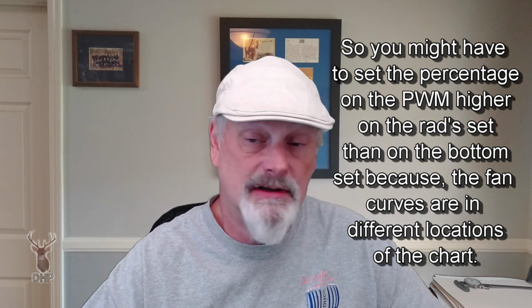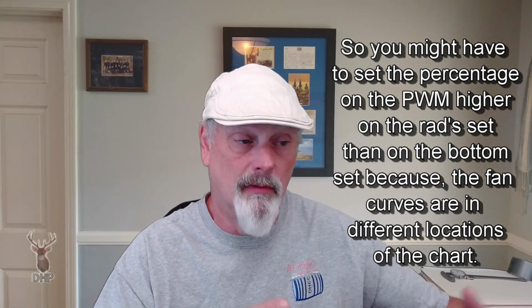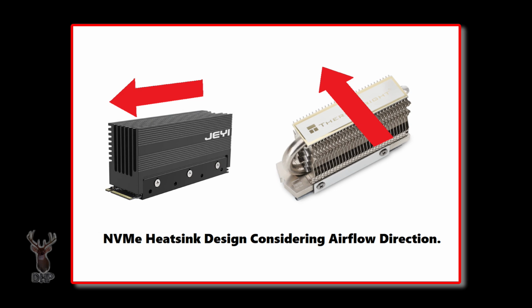Now, most of the new cases that I've seen, they're not really designed for airflow. What they're doing is they're taking a volumetric effect to it. We're not really flowing across like a motorcycle's fins, okay? It's not water cooled, so it's got to flow over a surface area. And the bigger the surface area, the easier it is to get the heat off, which is why a high fin per inch count on a rad is more efficient, because the closer you get those fins, the more surface area you have.